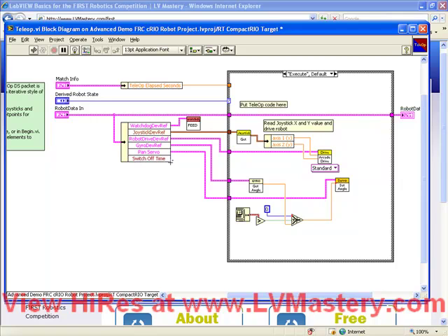And let's observe reconnecting this to here. I see a lot of new LabVIEW programmers simply doing this. Clicking once, dragging, and letting go on the second terminal. This isn't necessarily a bad thing in that the connection is correct, but if you take a look at this block diagram now, it's impossible to tell what's going on in this comparison function.